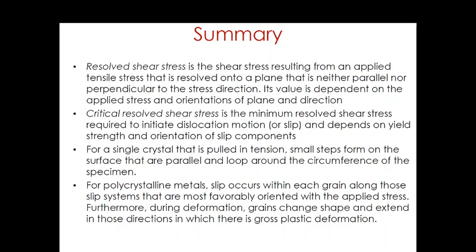The resolved shear stress is the shear stress resulting from an applied tensile stress that is resolved onto a plane that is neither parallel nor perpendicular to the stress direction. Its value is dependent on the applied stress and the orientations of plane and direction. Critical resolved shear stress is the minimum resolved stress required to initiate dislocation motion or slip, and depends on yield strength and orientation of slip components, that is cos phi, cos lambda.